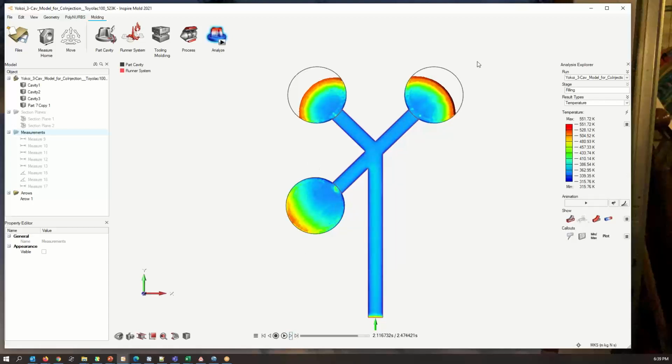This cavity is now full, and these two cavities are not, because what happens is it turns this corner, and I'm shear thinning here, and I'm actually creating a shear flow into this direction versus these two. For a long time, many of these molding softwares were not capturing this kind of effect. It would show all 3 cavities filling at the same time, and that's just not what really happens. There are lots of other examples of this kind of thing.